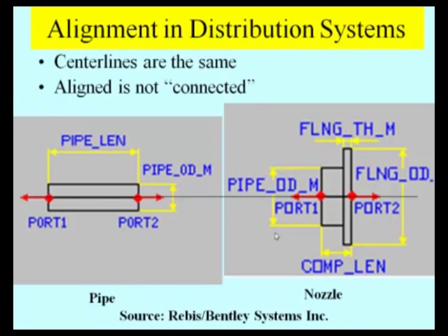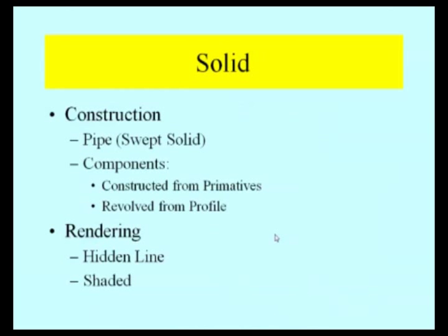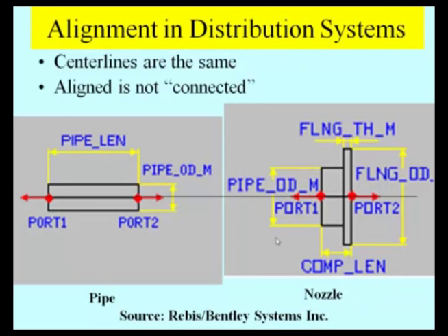So if I tell 2 things that they're aligned, I'm telling them that one vector in that component has the same direction or an opposite direction as another vector in the other component, and they have a point in common. Like the Earth has an axis, okay? That axis is a location and 2 more numbers. The only thing you don't specify on the Earth is where around the rotation you are. So if I aligned it, I have an axis. Now, you ever see an exploded drawing of a pump? All the parts are exploded out on their axes. Those parts are aligned, but they're not connected. See, so alignment and connection are different issues.